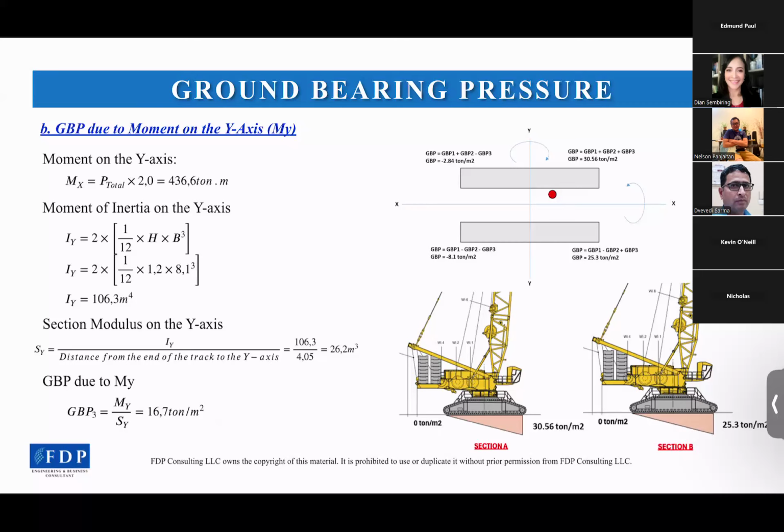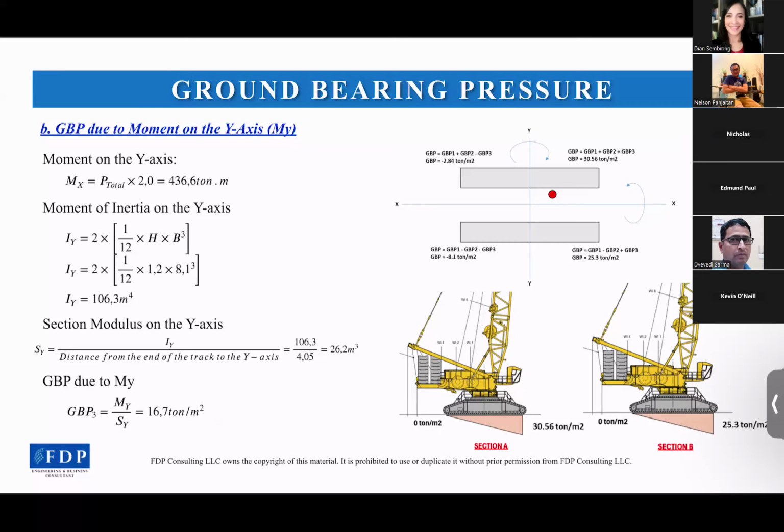From an engineering point of view, there is no correlation between the width and length and the mechanism of how the load will be distributed. As I mentioned before, it's about the thickness and the properties of the bearing pad.